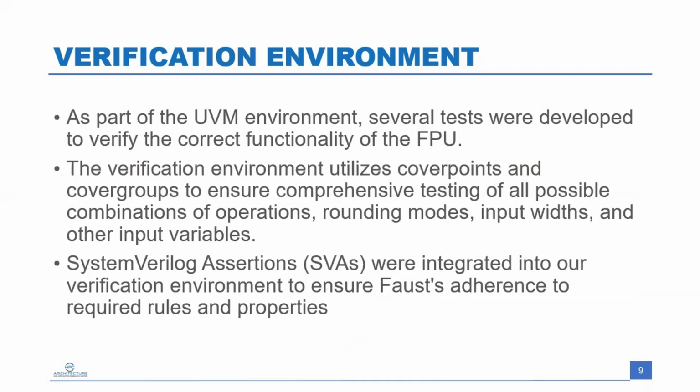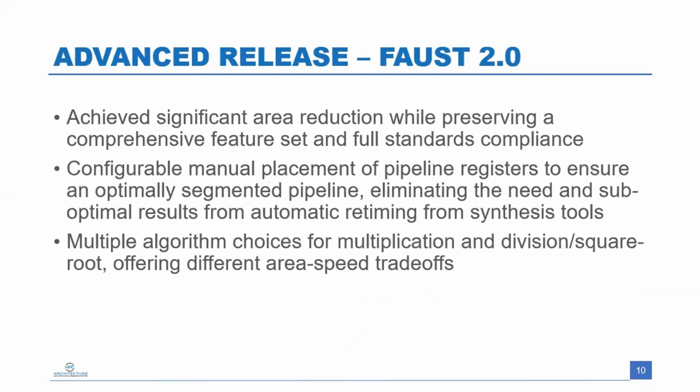And of course, the UVM environment itself is very much used in the industry, so it can be easily integrated in the industrial process of verification of the chip. We have also used SystemVerilog assertions for some of the things so that the whole environment is very efficient.